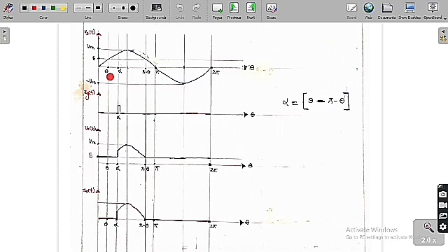So this thyristor will be in reverse bias, which means simply that a negative voltage is going to occur across the thyristor. So it is an open circuit. Therefore the output voltage is equal to the value of E up to theta, whereas the load current is equal to 0 up to theta.